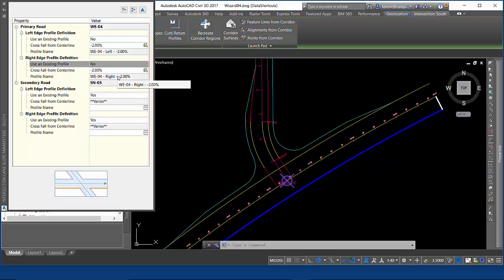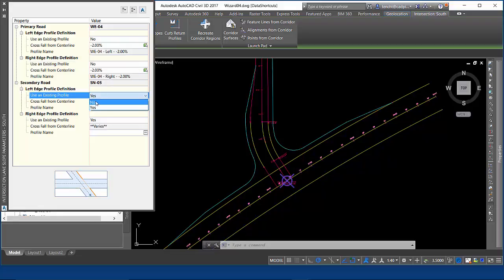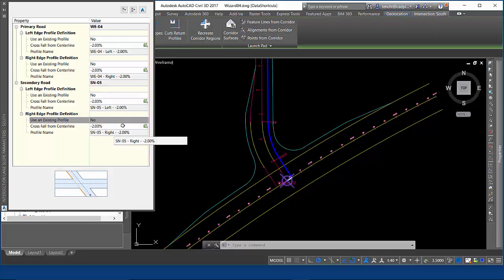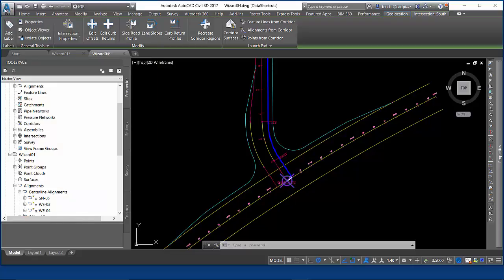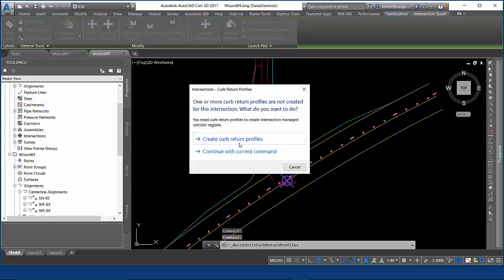Maybe I can put a superelevation value in. If it's all a steady curve here, I can throw a superelevation value in and accomplish that at this point in the design as I build my vertical here. For south to north, I don't have those yet either. So I need to turn those on, and the calculation and the naming rule. You get the naming rule based on the values in your template, whatever you want to change the crossfall to. And so we're going to leave those alone at this point and build those two. So now we've got the lane slopes for the bottom, and now we need to do the curb returns.